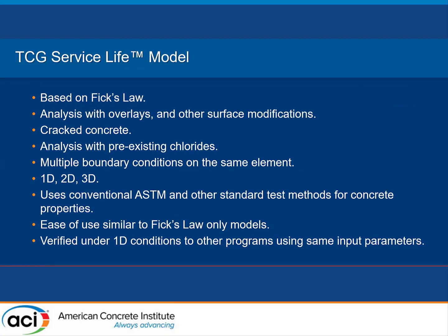The model that we are developing, or starting to introduce, is also based on Fick's law. It can analyze overlays and other surface modifications. We can look at the effect of cracking on concrete. As mentioned by Doug in the program at Toronto, we do pre-existing chlorides. We have multiple boundary conditions on the same element, so you can have a part in water and a part in air. 1D, 2D, 3D configurations can be used.